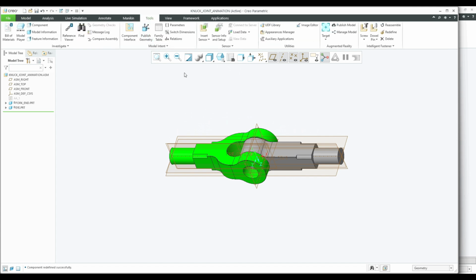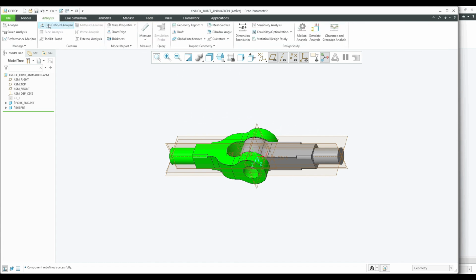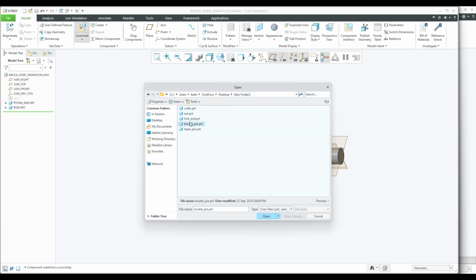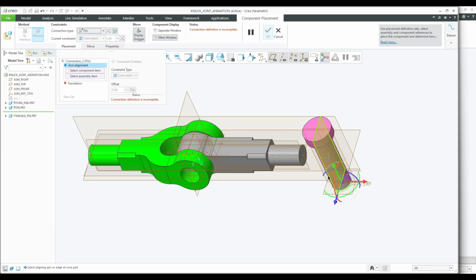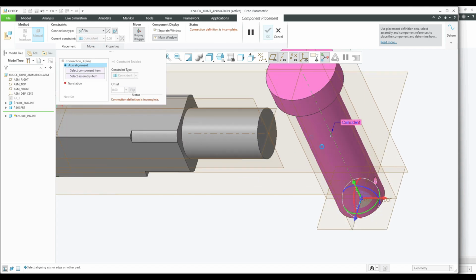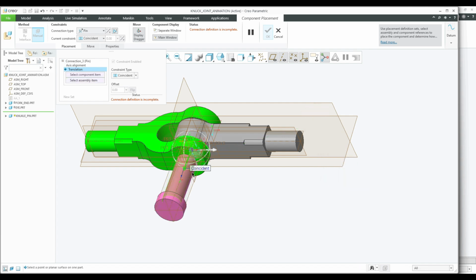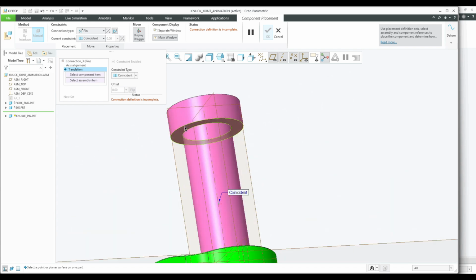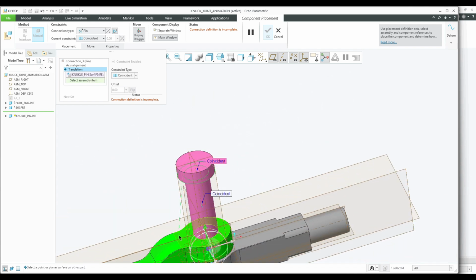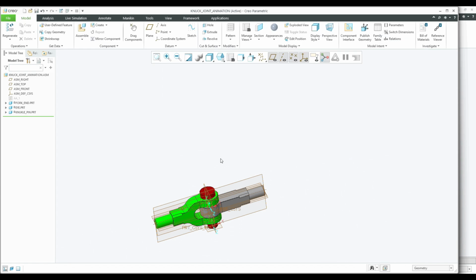In this condition itself, I would like to continue. Okay, I will make a knuckle pin. For the knuckle pin, we don't want any independent rotational movement. It just needs to be fixed with the components. So here we are not going to select any rigid connections or slot connections. We are using only pin. I will make it axis to this axis, and this surface will be placed to this particular surface, and we are going to give the constraint.